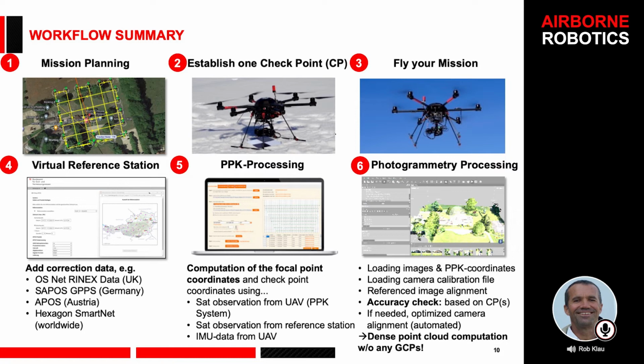But I guess just to reiterate a bit, this is how we're breaking away from the traditional, old method of putting GCPs all over your site. You might need a dozen of them, you might need 20. If you're using those smart ones, you've got to go and put them out, then go around at the end and pick them all up again. I don't think it's that smart. What we're doing here is direct georeferencing: knowing your camera parameters, all those lens distortions and so on, and knowing where the camera is, it's like forward engineering.